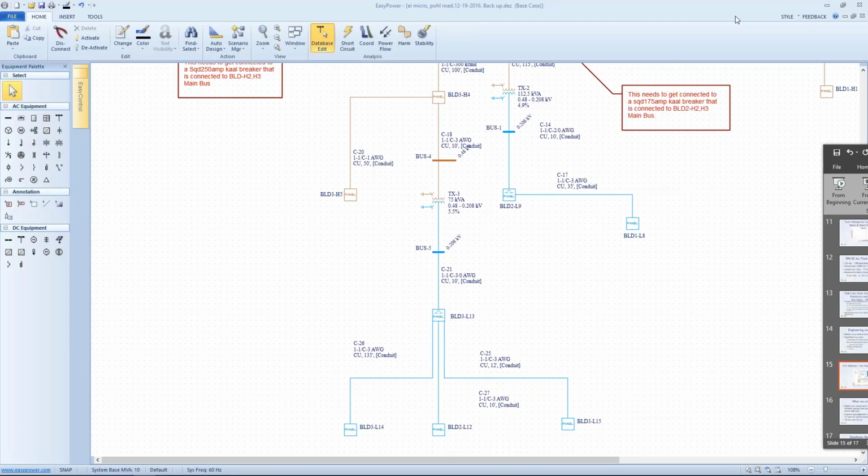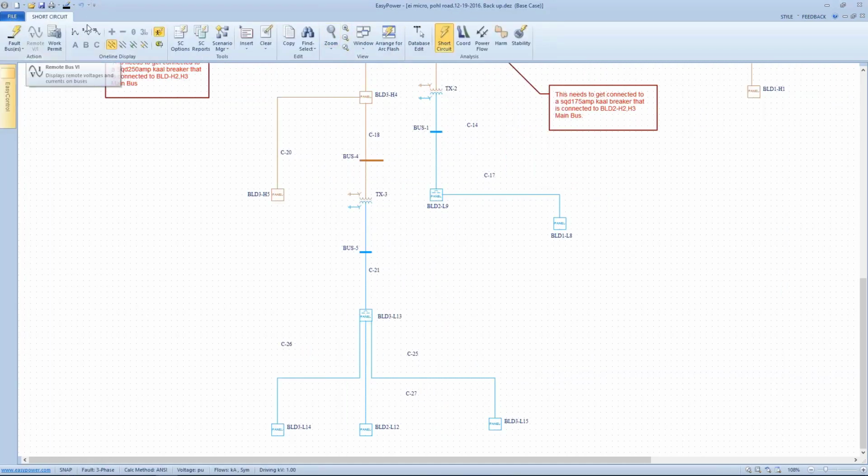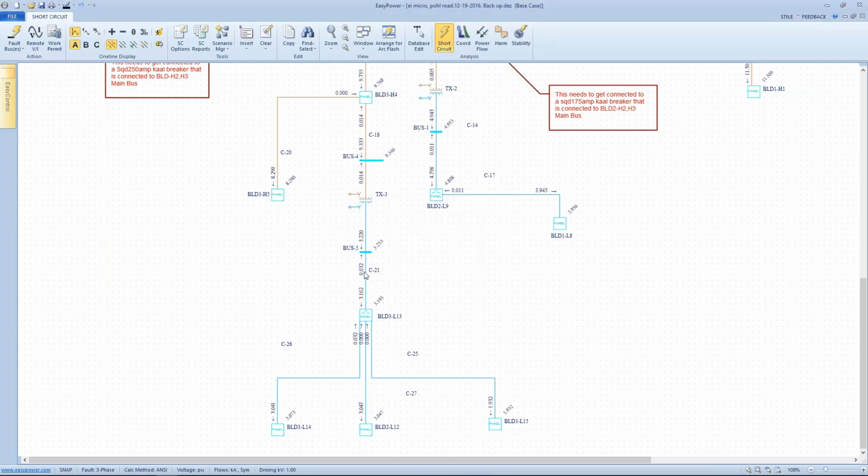All right, so what we're looking at here is a larger system that has 208 volts supplied both by a 75 kVA transformer and by a 112.5 kVA transformer. And just with the basic setup, we go into arc flash calculations, and what I recommend in any system that I'm doing analysis on is to look at the current first. And you'll notice that was the baseline for most of the reports and the research being done.